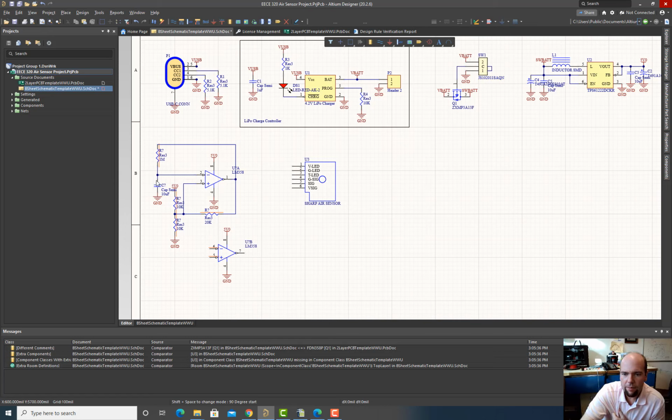But when the capacitor is discharged, then this voltage here is definitely going to be lower than over here. So the op amp is going to amplify this, and it's going to produce a very high rail out here. So when this is discharged, this is 0. This is anything other than 0. It rails. So this rails high. When this rails high, this resistor pulls this voltage up. So it pulls it a little above 2.5. So it's going to be something like 3 volts or so.